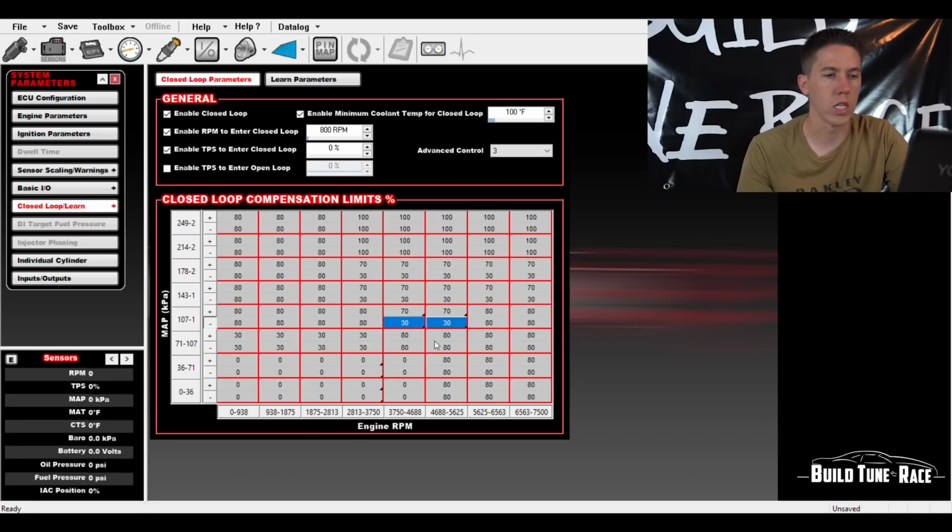It's still aggressive. I feel that once you have your fuel map dialed in, you should pull those numbers back in case you have a sensor failure. All the EFI cars are great. They work super, super well. But when you have a sensor failure, it could go one way or the other, and then it tricks the system into doing something else. So when your fuel map's set, you can lock those numbers down. You can literally tell it to not adjust any.